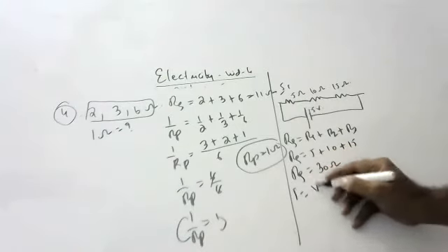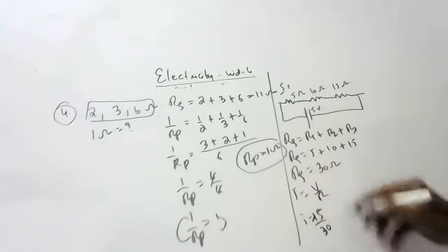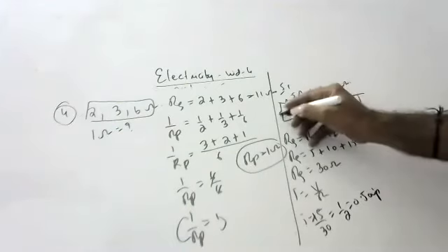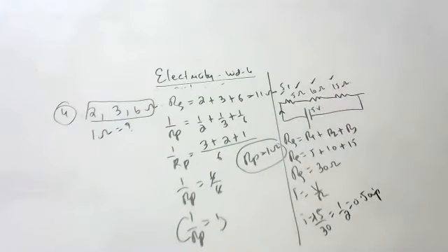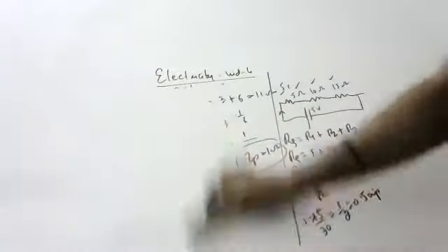Now I is equal to V by R. I is equal to 15 by 30, 1 by 2. That is 0.5 amperes. In all of them 0.5 amperes only will flow. Like that we have to do, children. So you should know when you are doing the sum what you are going to do. After putting the pen on the paper, you should not think. First only you should know what you have to do.